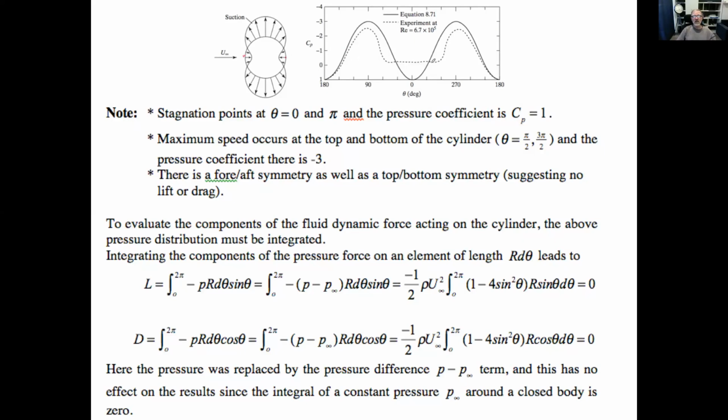Again, here's the pressure distribution, which we mentioned. Velocity distribution is actually twice the free stream, and it's -3 in terms of Cp. So you have to get used to the Cp, or else you can use velocity. So it's going to be 0 here and 3 times the velocity here. Okay. And we're looking at the solution.